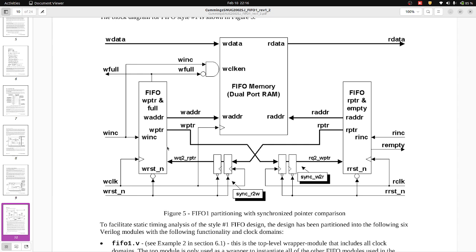But in reality, when the chip comes, or when we do a gate level simulation, there are delays. So how will the transition occur? It might go from 0 to 1, but there are different gates, so they will have different delays.